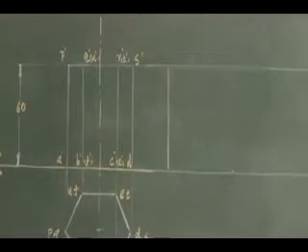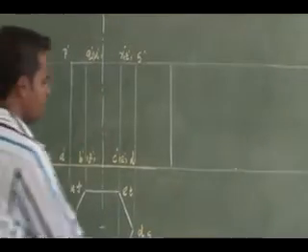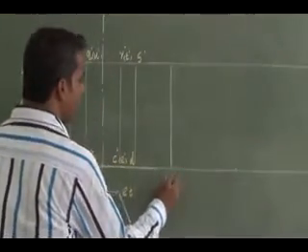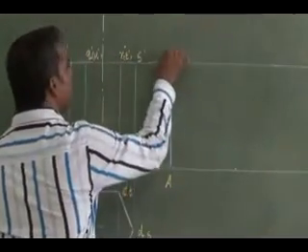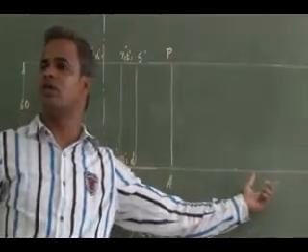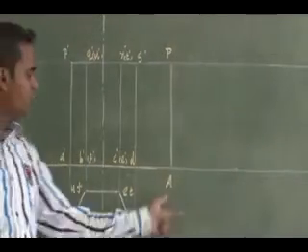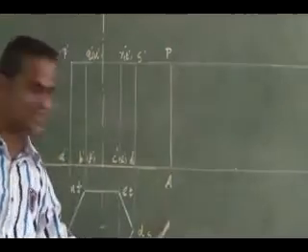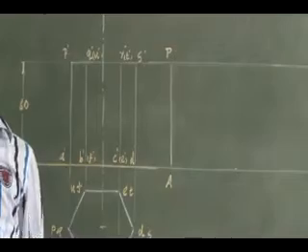That is the location I am going to open the solid, and that is the location I am going to hold it and form the prism. So I can have a notation A and this is my P. In your development, you give the notations in capital letters. This is my first vertical edge, A and P. From there I am opening, and from there I am going to close that solid and form it.